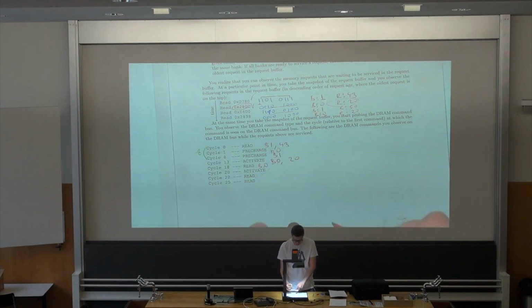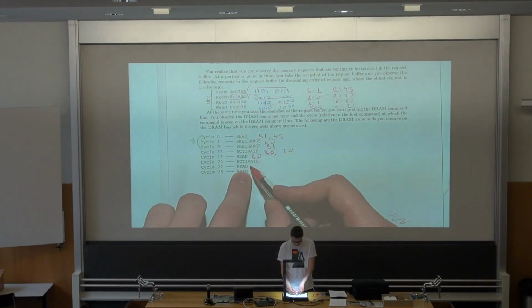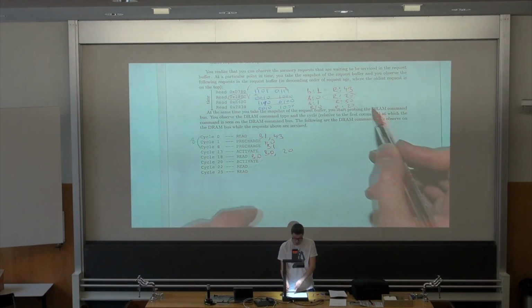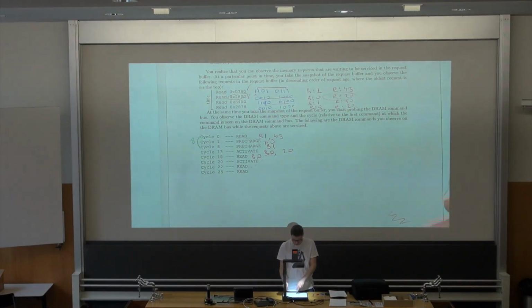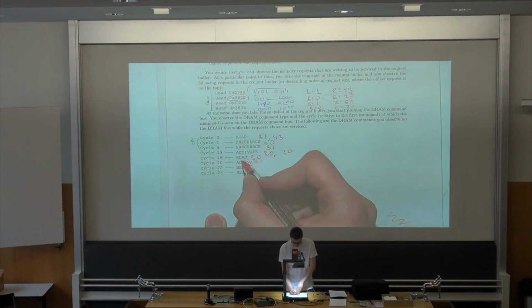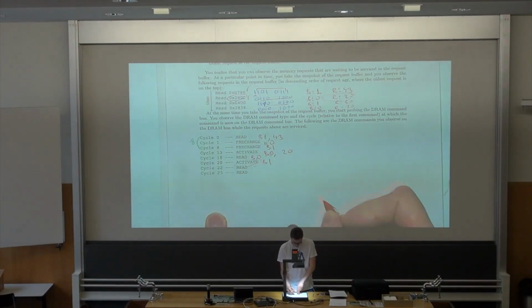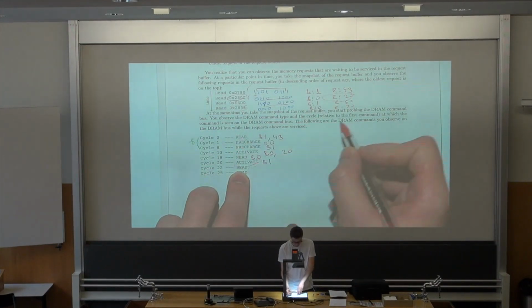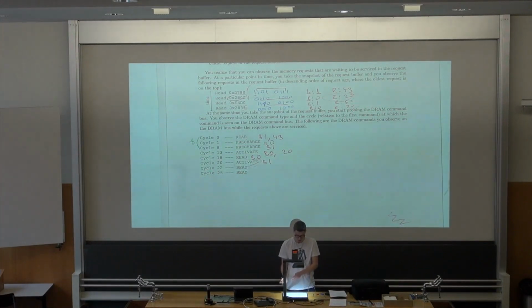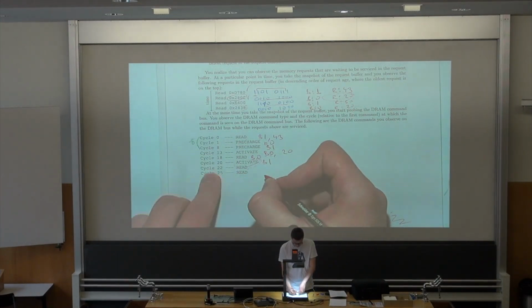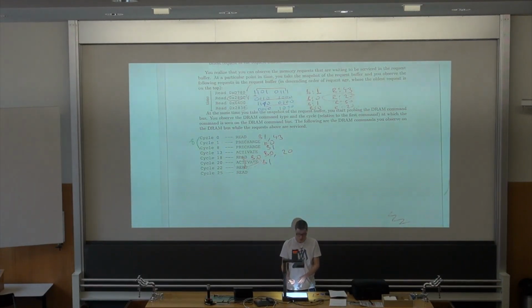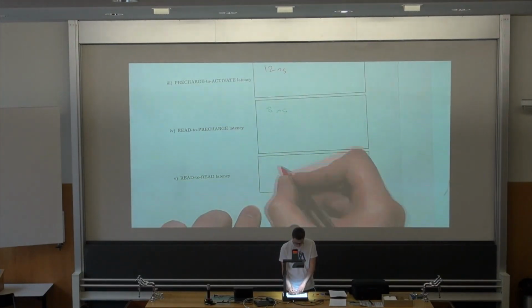Okay, so this part is interesting. We have 2 identical requests here to bank 0, right? They both target the same row, but different columns of that row. While this is being activated, so this activate is bank 1, we can service this last request from bank 0, right? Which also targets row 20. So basically we have a row buffer hit here. This is telling us the distance between 2 read commands, which is 4 cycles here. So read to read latency is 4 nanoseconds.